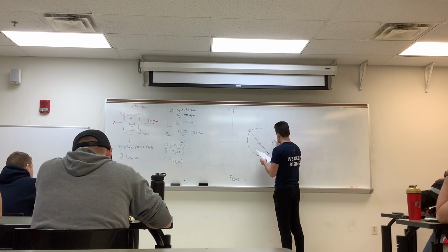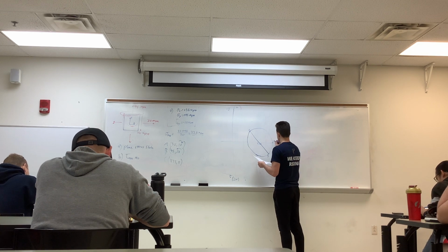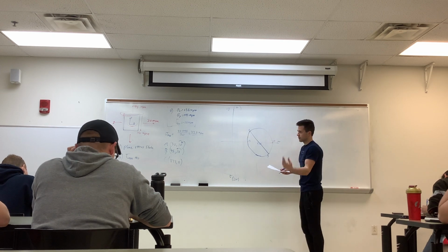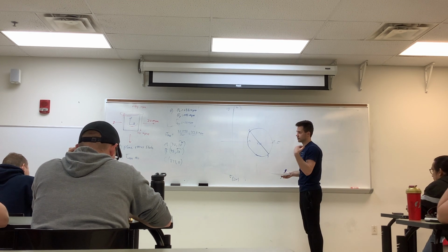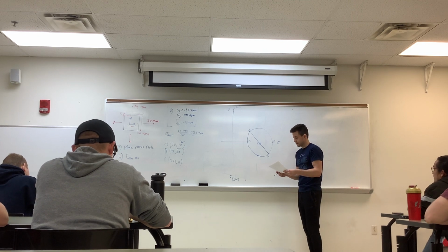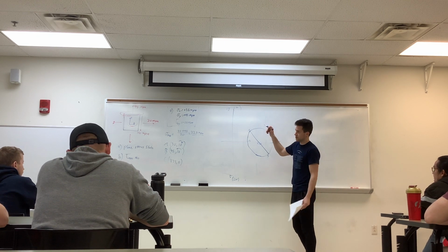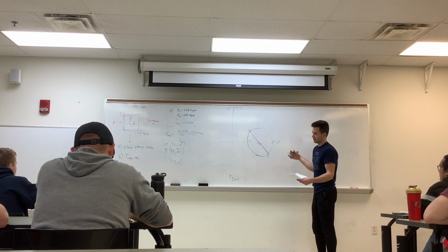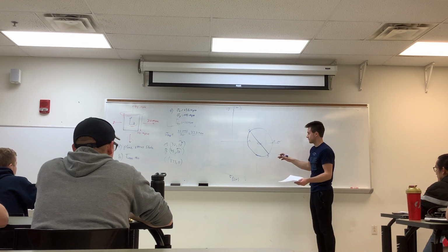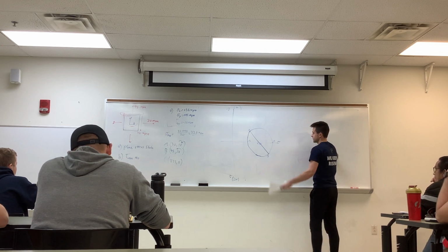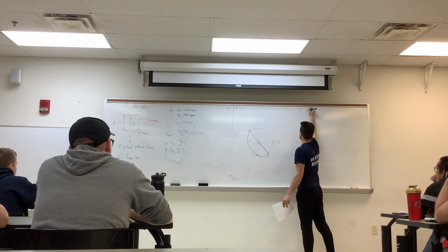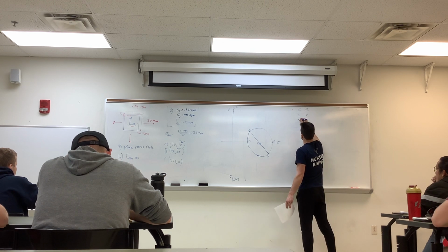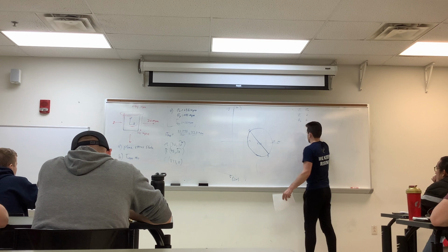So we now have sigma 1, sigma 2. When we were talking about our absolute shear being our radius, that's with regard to the total state, because our absolute shear may not necessarily be in this element. So when we first introduced the third dimension, we have three separate circles. We have the Mohr circle between sigma 1 and sigma 2, between sigma 1 and 0, and we also have between sigma 2 and 0.